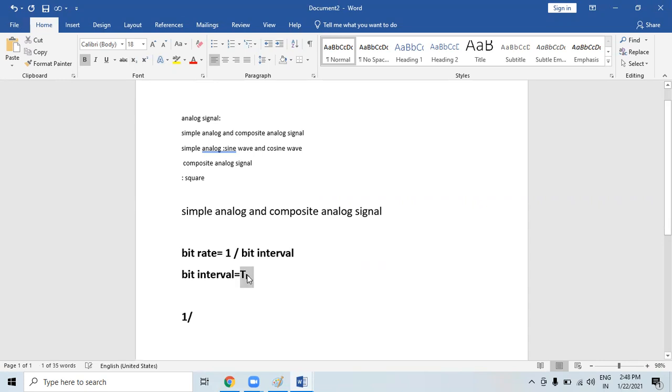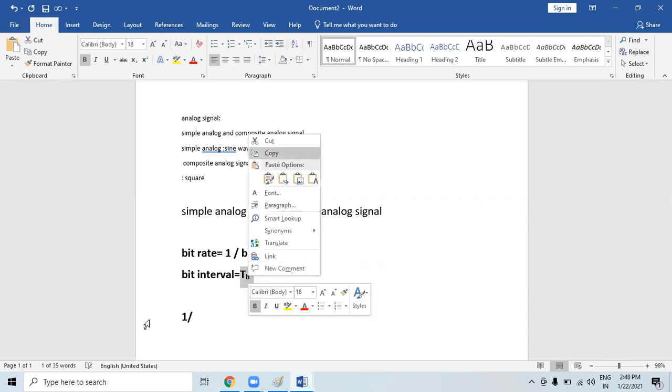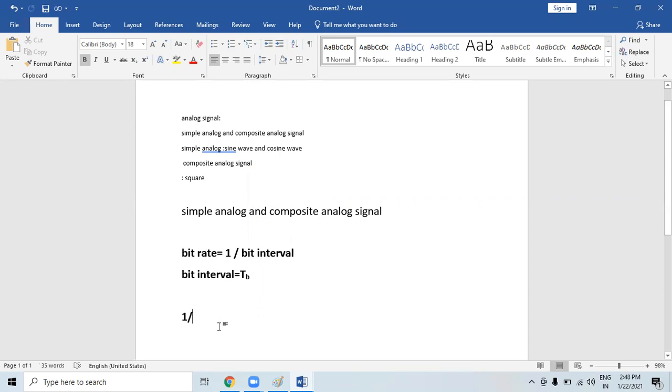This is the formula of your bit rate. Bit rate is also called signaling rate, and it should be as high as possible. However, with an increase in bit rate, the bandwidth of the transmission medium channel must be increased in order to ensure that the signal is received without any distortion.